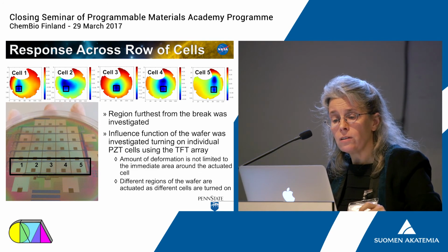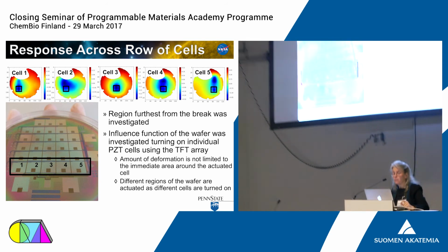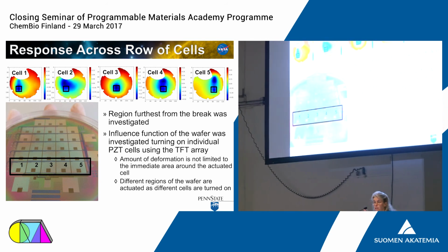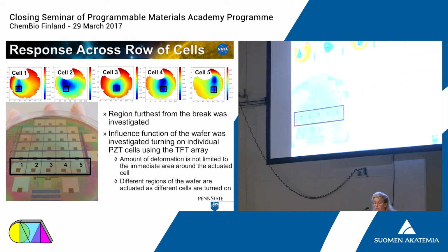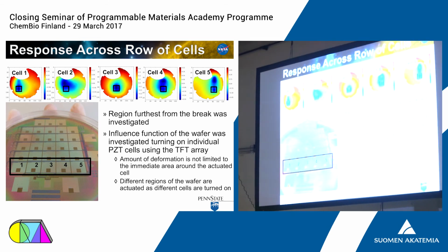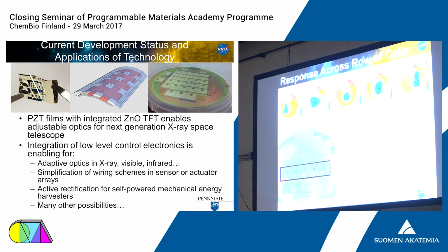But what you can see is as we progressively actuate 5 different elements on this device, you can actually move the deflection patterns. It's not perfect. You see a lot of coupling along the columns. That coupling is probably associated with damage of the aluminum oxide dielectric when we broke that device.